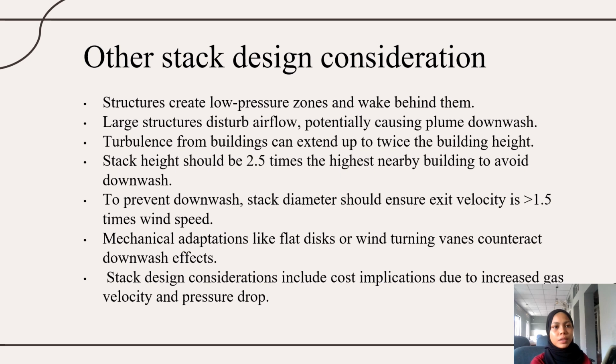Next, we will go for the other stack design considerations. So we have eight other suggestions. The first one is that structures create low pressure zones and wakes behind them. A large structure can disturb airflow and cause plume downwash. And the turbulence from buildings can extend up to twice the building height.